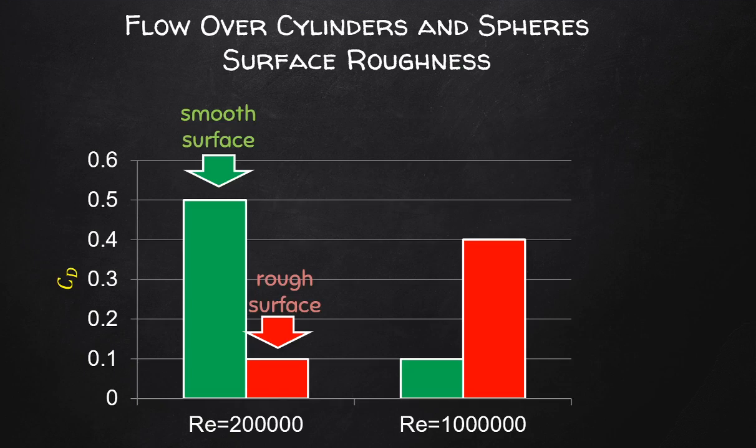But this is not always good news. Once flow reaches very high turbulence, the boundary layer that forms becomes thinner and thinner, and it can so happen that a very rough surface may begin to experience very high frictional drag forces, and due to these frictional forces that are created by the rough surface, we obviously end up with a higher friction factor. Okay, so much more